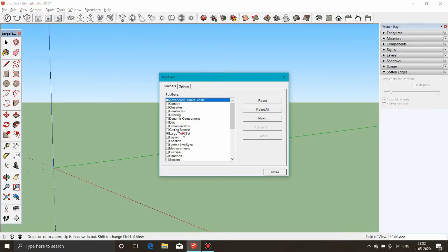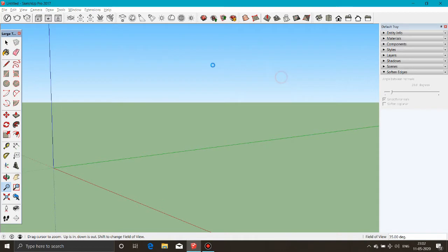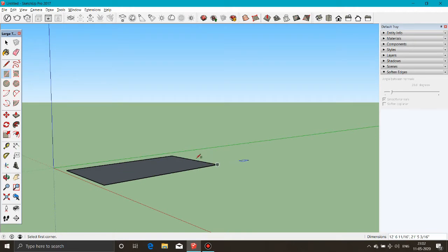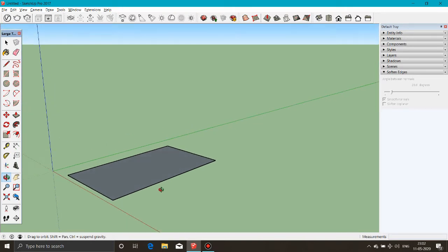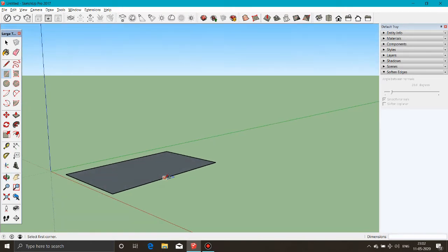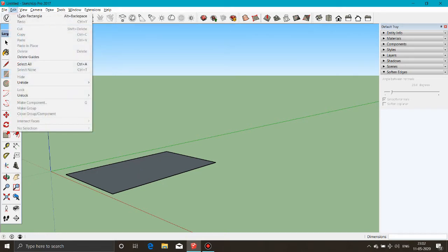To start this model, let's draw a basic rectangle. As we learned before, everything in SketchUp has real dimensions. We need to control what the dimensions are. In SketchUp, to enter dimensions, you start an operation and simply type in the desired dimensions. Try this. Undo your rectangle if needed, then start drawing a new rectangle.